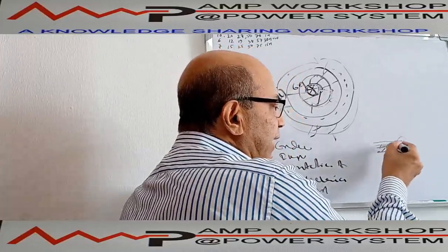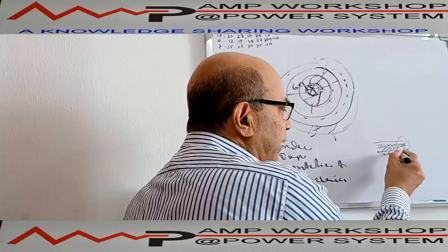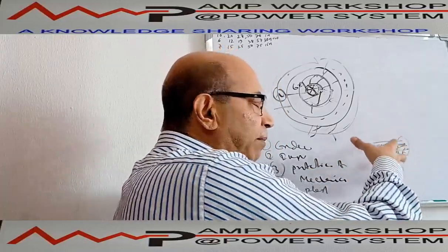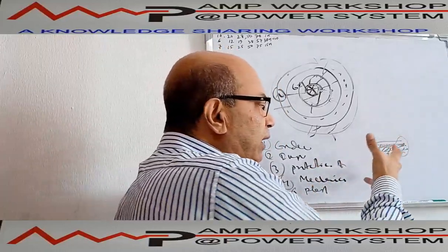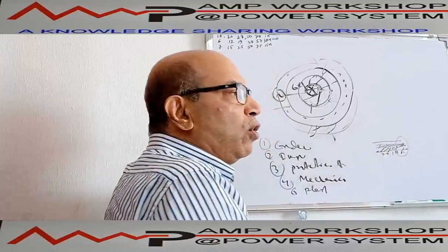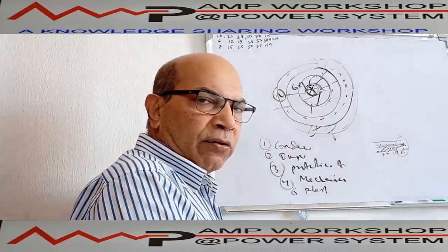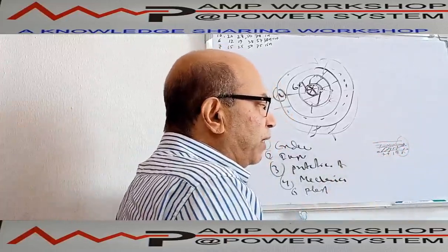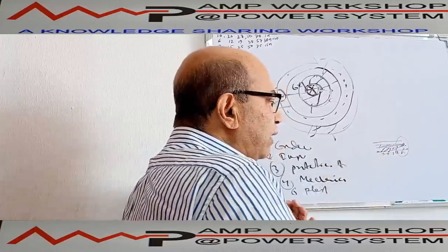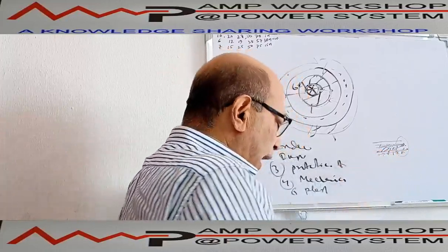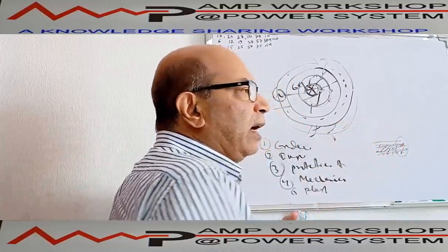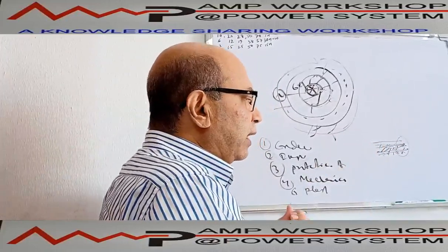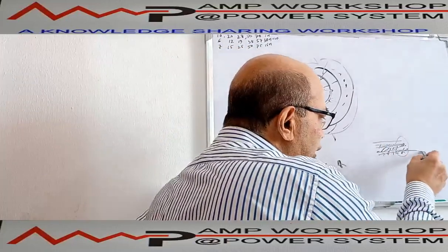When it acts as a capacitor, there will be charge over here. What can happen is this charge will come in contact with the earth, then the gap between these two will be ionized, and ozone gas can be formed by the decomposition of the air, or this charge can cause a voltage on this surface, and that voltage is dangerous for the cable or for this insulation. The insulation will get damaged. So what is the requirement? This charge has to be drained to the ground.